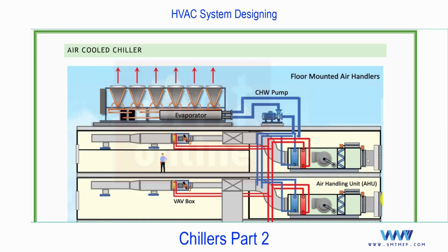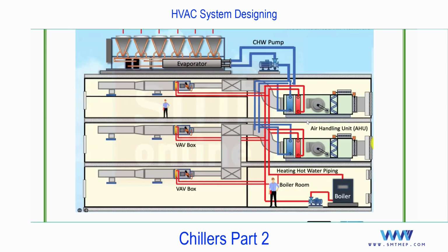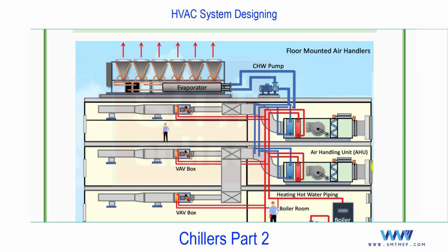First, till now what we discussed, this VRF system, the refrigerant is responsible to cool the air, but now in chill water system, the chill water is responsible to cool the air, and from the water we are going to reject the heat to the refrigerant. Okay, that is a major difference between the DX and the chill water system. So here you can try to understand with the line diagram. I'll show you with the drawing also, but first some idea.